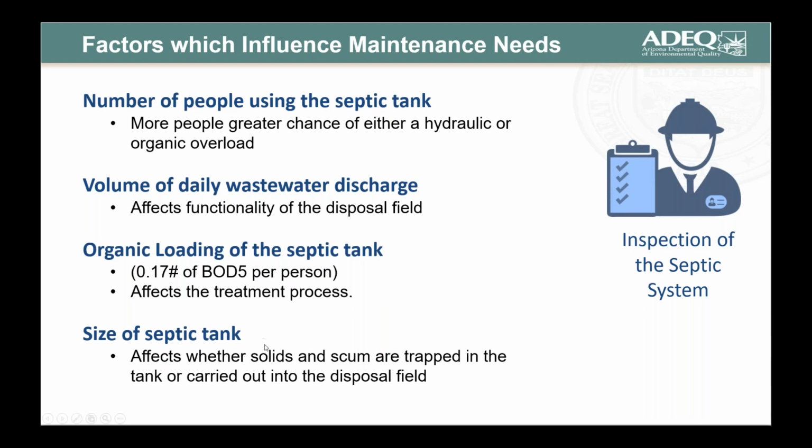And the less detention time you have in the septic tank, the less time there is for solids to settle out, and you're trying to avoid those solids being carried over to the disposal field. So if you have an undersized septic tank or a higher volume of wastewater going into the septic tank than it was ever designed to handle, you can have solids going into your disposal field and adversely affecting it.